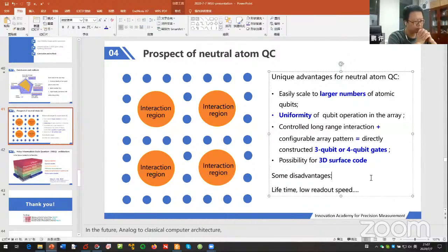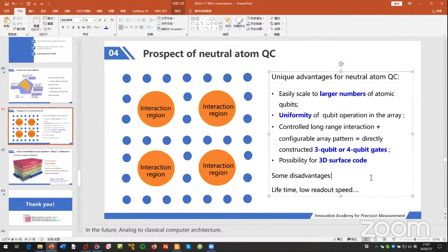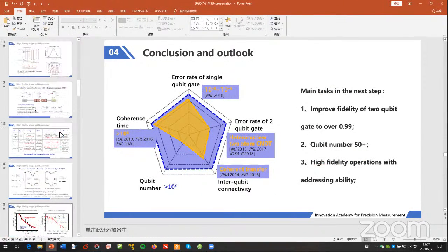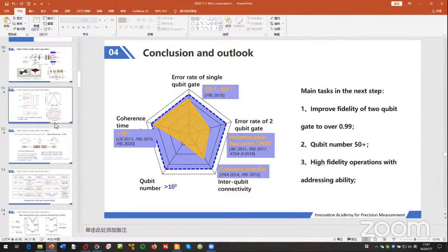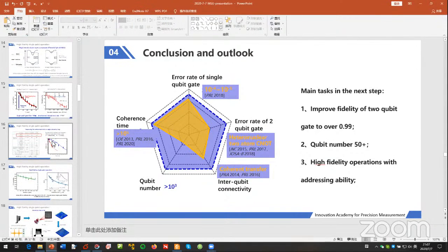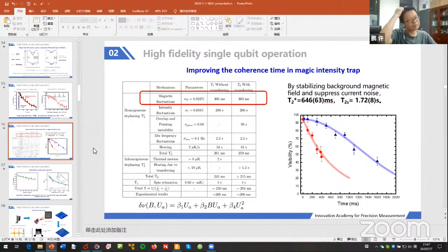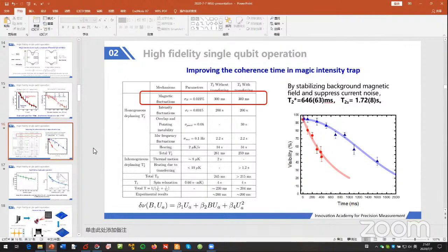So one last question is about the magnetic feedback you talked about in the first part of the talk. What kind of sensitivity does your error signal from your Gauss meter have, I believe, and what kind of feedback loop bandwidth did you require for this compensation?